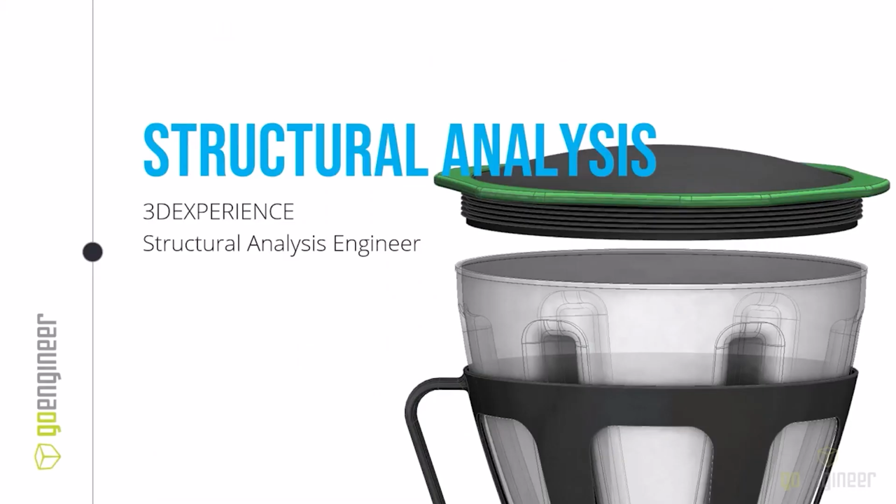So another structural analysis was the press of the lid onto the picture itself. Now we have the gasket seal, and I originally put 5 seals on this gasket. However, in talking with Matt Schreck, another engineer here, he said, there's usually only 2. So he actually modified the model, removed 3 of those seals on that. Now we know we need to press this lid on, and we want to keep the press force under 30 newtons, or roughly 6 pounds. Anything more than that would probably be too much for most people to press this on, or it would just be a bad experience.